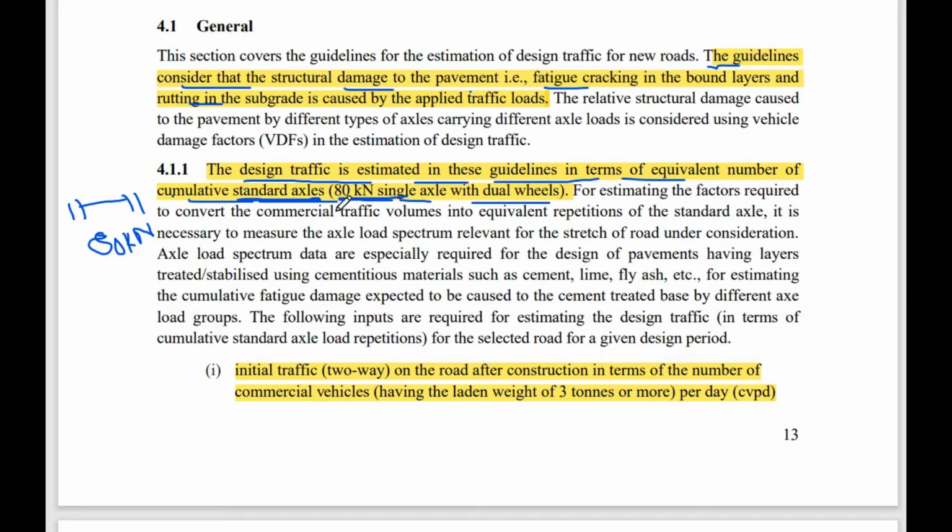So if we have multiple axles, that means an axle which has a 160 kN load, we will say it equals two standard axles, that means 80 plus 80, that means 160 kN load. If a particular axle has this load, then we say that it has the same impact as two standard axles. So this is all about the standard axle.